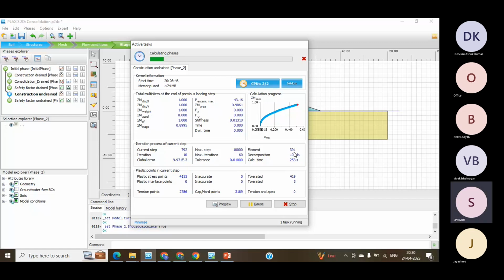Okay, so if it is 102, then come back and change that particular step alone. You can change the maximum number of steps to some 1,000 steps or something, and then solve for this. Now in my observation, I'm solving up to some 1,000 steps, and I see that the criticality is happening at 391.